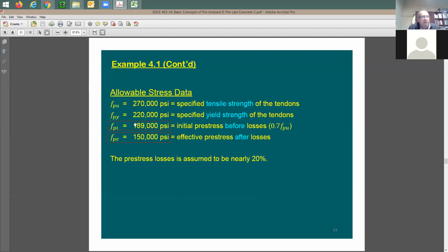Now, you apply this, and then all of a sudden you see the stress is dropping down because of the material relaxation of the steel. The steel is going to start to relax a little bit, and also you're going to have losses in concrete because of shrinkage and creep. I'm sure that you guys maybe heard about this term, shrinkage and creep. Shrinkage, because cement, or any cementitious material, is a shrinkage material, which means it's going to shrink, it's going to reduce in size.